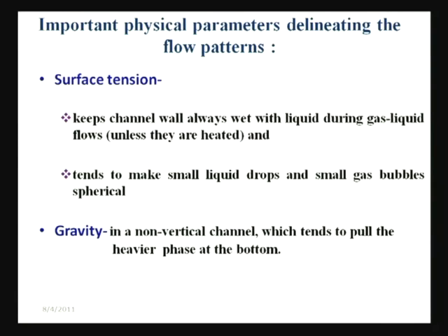Now, remember that the first point which I have mentioned can have certain exceptions. For example, when the tube is heated and the wall temperature is much higher than the saturation temperature of the liquid, vapors will be generated at the wall and they may try to stick to the wall up to a particular distance.